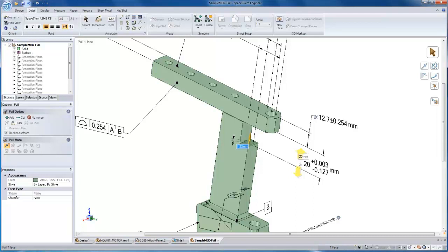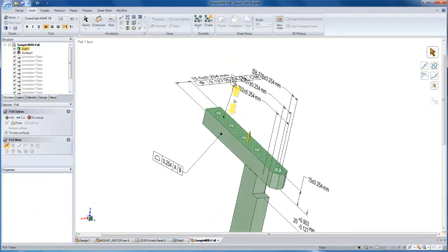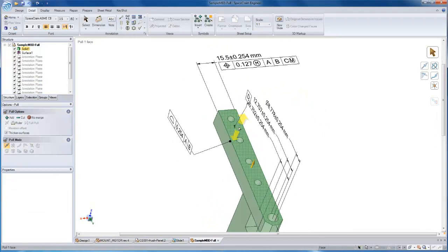And so any dimensions you see on the screen, I can go modify the geometry using those dimensions as driving dimensions, although they're actually annotation dimensions. Even if I have symmetry, or if I want to preserve symmetry about a couple of faces, I can still do that. I could say, let's make that 20.